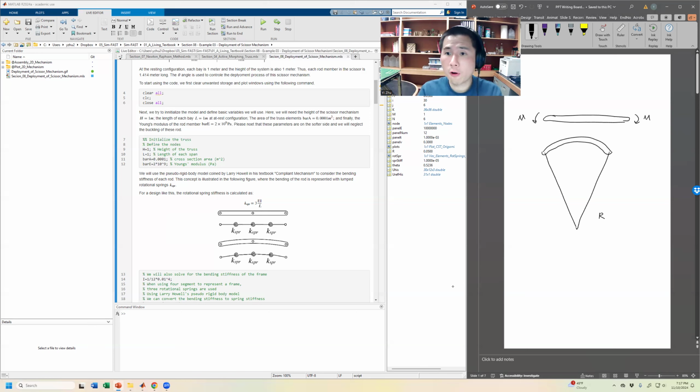And if we recall some of what we've learned in the fundamental mechanics classes, what we realize is that the governing equation for a beam like this, theta over ds, would be related to M naught, which is this moment that we apply to the beam, over EI. So I is the second moment of inertia of this beam about the bending direction, and E would be the Young's modulus.